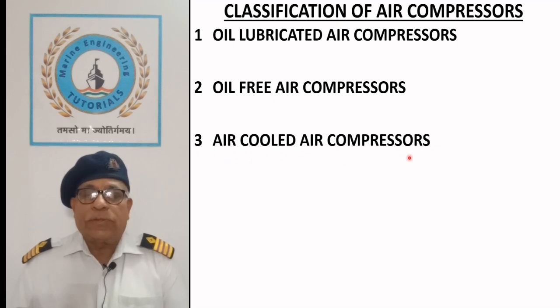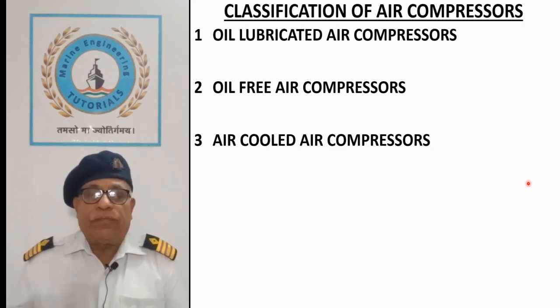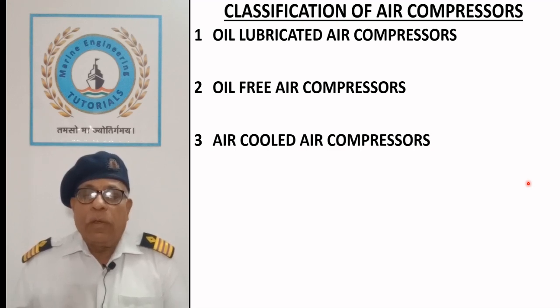Air-cooled air compressors. Air-cooled compressors are used on ships for small applications such as emergency air compressor, service air compressor, breathing air compressor, or deck air compressor. Air-cooled compressors have no corrosion or intercooler fouling, but run very hot and radiate a lot of heat which requires a special trunking.